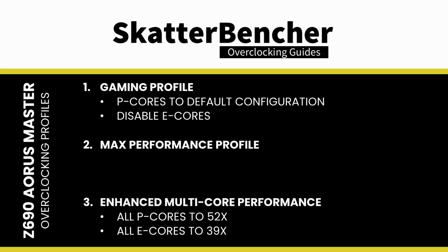So the CPU goes from 16 cores with 24 threads to 8 cores with 16 threads. Max Performance Profile sets the P cores to 5 GHz and the E cores to 3.9 GHz. It is important to note that only the Enhanced Multi-Core Performance Profile is in fact overclocking your CPU. That's because it runs 6 out of the 8 P cores higher than specification. The 2 other profiles are not actually overclocking, as they run all cores within voltage and frequency specification.